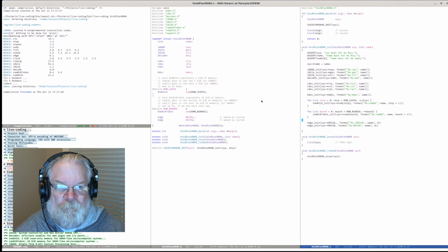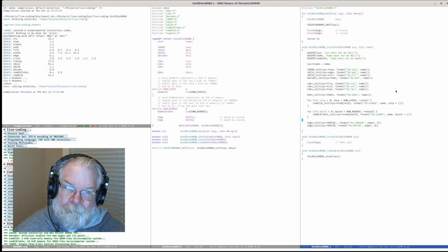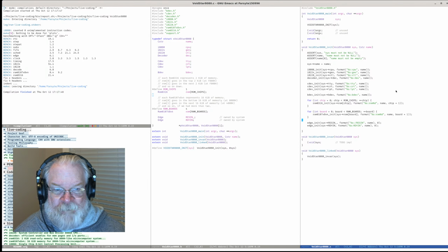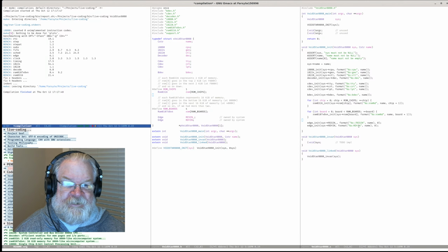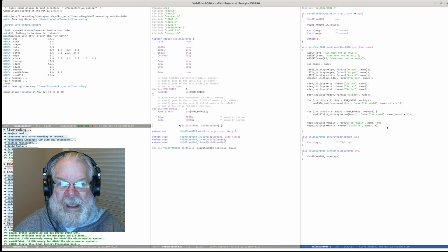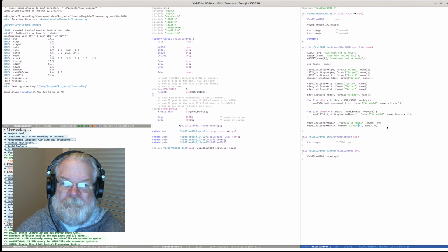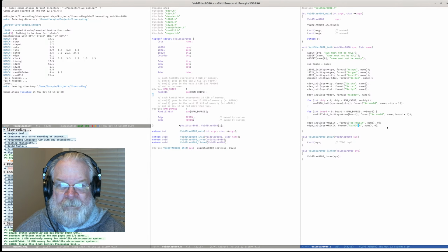This maps into the way you would start an 8080 from a front panel if the system didn't do a whole bunch of stuff for you, which is literally you hold down those two, bring the power up, release the reset, and then release ready. Now, in our system, because everybody is talking to the same ready pin, whoever set it last wins, because we are not doing tracking of, I set it and I'm holding it. I'm setting it and I'm leaving it. So it's all fire and forget.